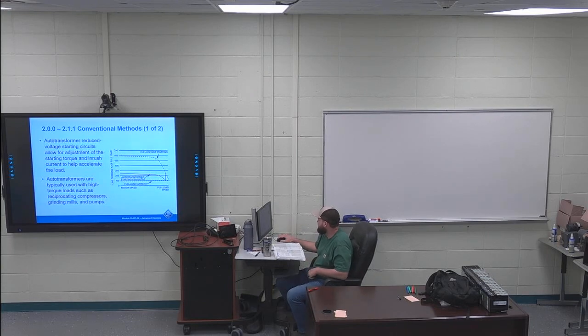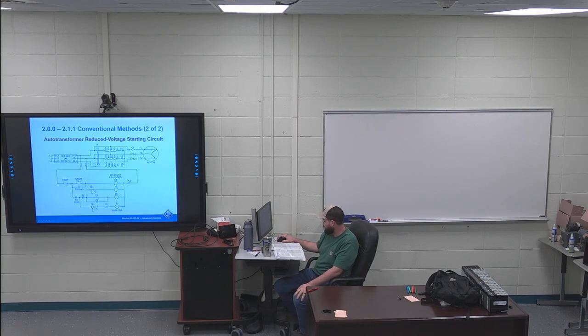You're going to have this figure 12 on your page 15. You're going to need to look through this. So you've got auto transformers. Remember, in an auto transformer, the primary and secondary coils are one together, wired in series. So this is like your primary and your secondaries. You have 3 separate auto transformers that are wired together. And then you just need to follow along as I'm reading through this schematic.